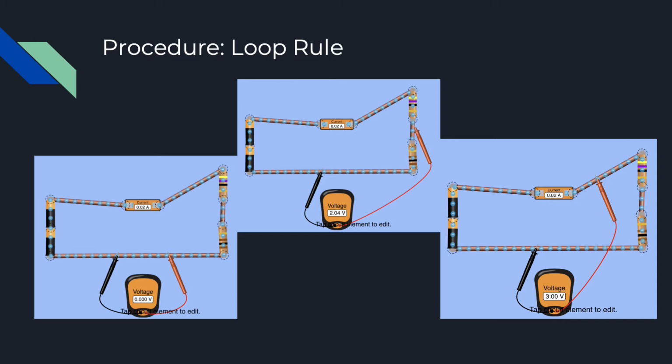That is because 1.96 volts have dropped through the 47 ohm resistor, leaving 2.04 volts left. And in the last picture, there's a voltage reading of 3 volts because the ammeter has no resistance technically, and therefore it is the original EMF that has been retained.